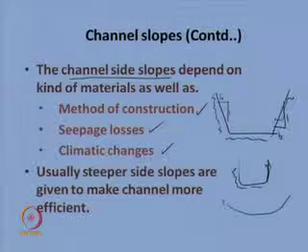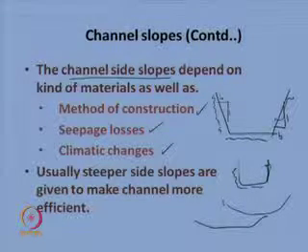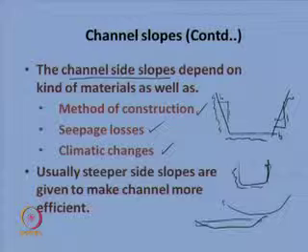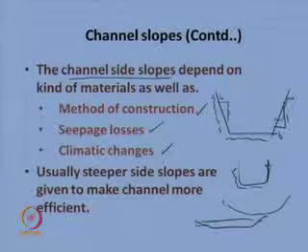So, usually steeper side slopes are given to make the channel more efficient. We will discuss this later today. If the side slopes are steeper, that channel is able to carry more water compared to shallow or non-steeper side slope channels. So, those things also come into the picture.